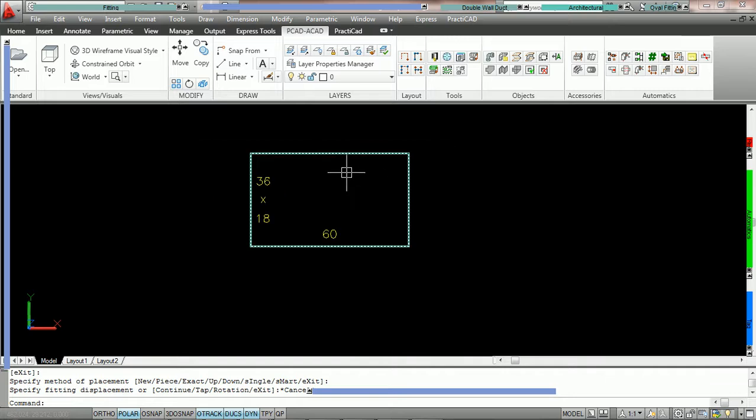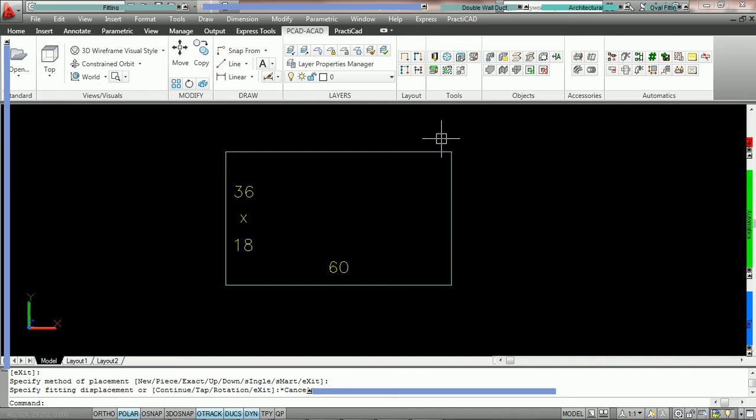However, the problem with this is we no longer have a flange sticking out so that we can do collision detection on our drawing. So what we'd like to do is add an accessory to this connector so that we see a flange we can use for collision detection. But that flange doesn't actually take away any length or material from the fitting itself.